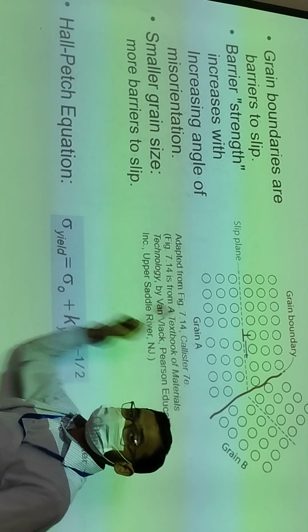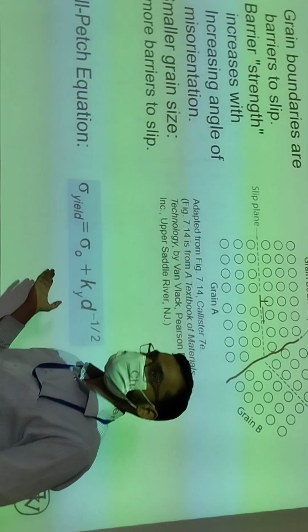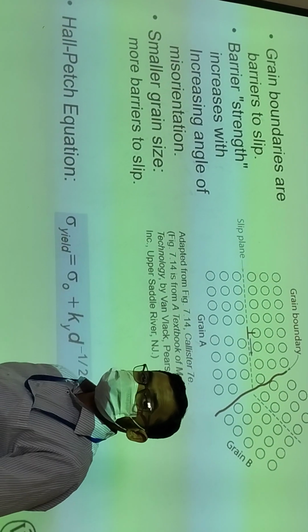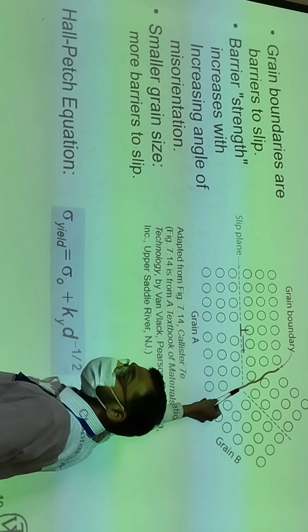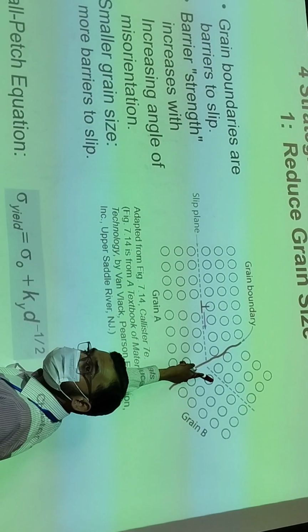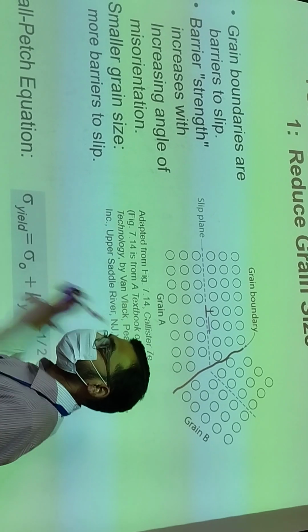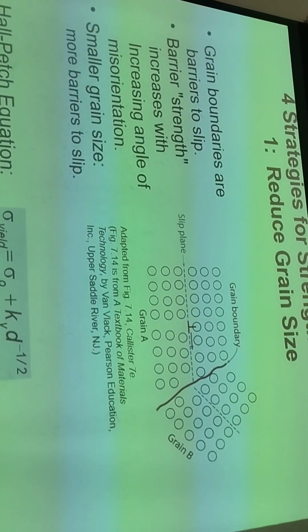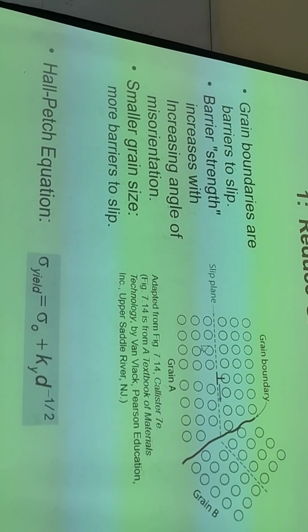The slip plane has changed. So what is going to happen? This deformation which was moving in the x direction has encountered a physical barrier. After that, it has either to move in this direction or it has to encounter planes which are going to have a different kind of strength as compared with this direction.